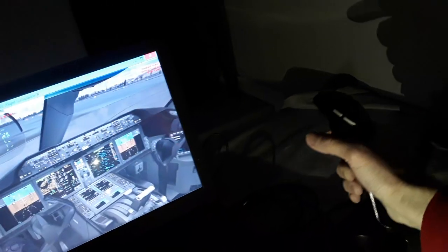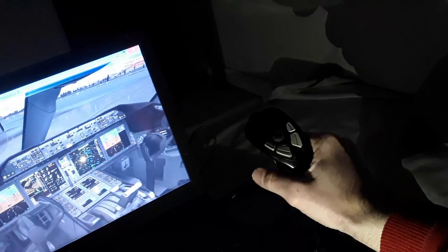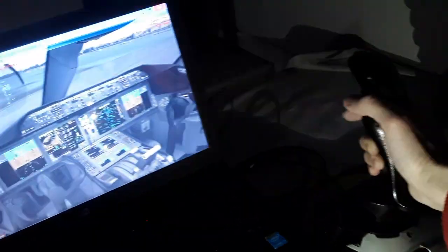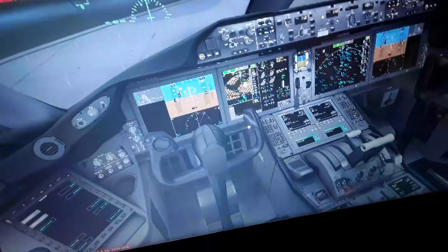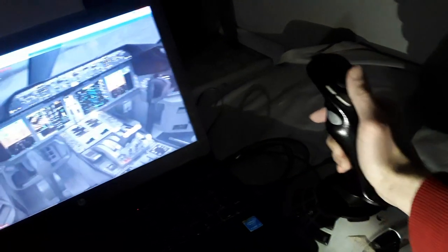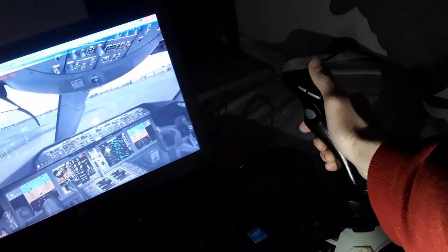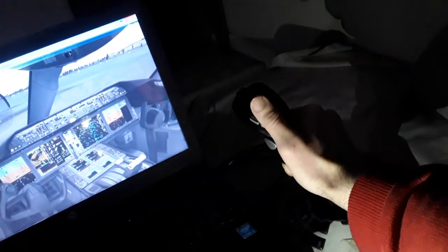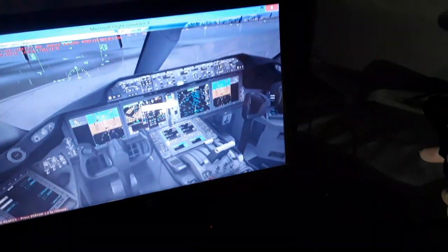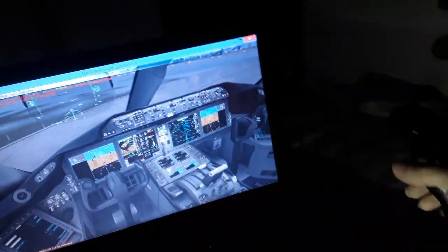So this is the roll control, the longitudinal axis, or aileron spoilers, the control wheel as you can see in the Boeing aircraft, the side stick left and right. So we have the pitch axis, the elevator of the aircraft, control wheel, ailerons, spoilers and flaperons, and the rudder, the yawing axis, rudder pedal, nose wheel steering on the ground, and also the toe brakes of the rudder pedals.